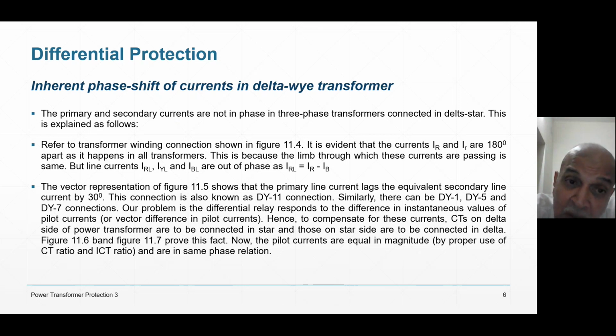And third harmonic, if it passes through transformer, the eddy current losses are proportional to square. So eddy current losses will be 9 times. However, the magnitude is less, but because of frequency, it is 9 times. It can damage the transformer. It can damage the insulation of the transformer. And if you allow further, then if it goes to generator, generator will be certainly damaged due to harmonics. Generator can withstand only 5% of negative phase sequence current.